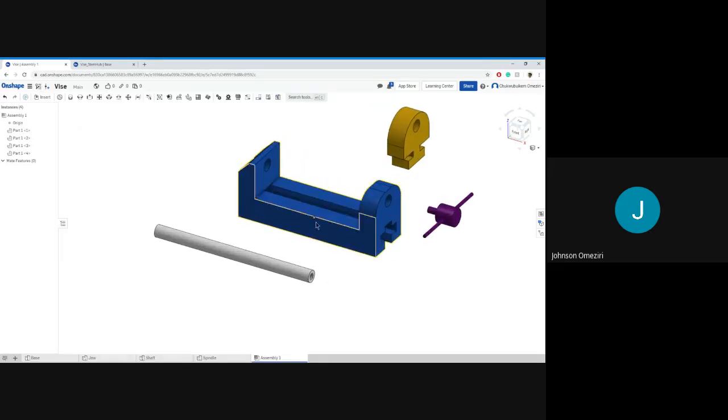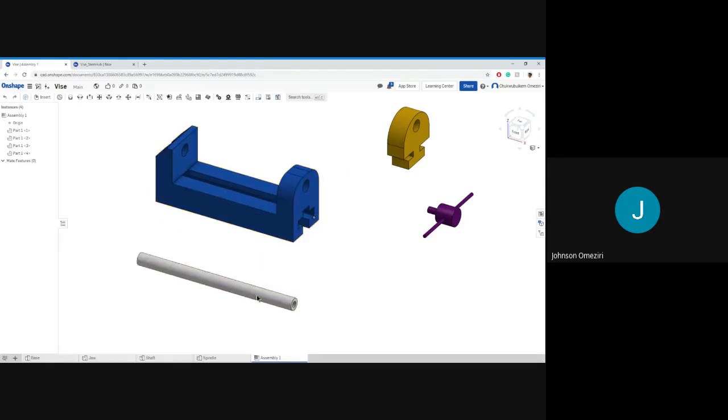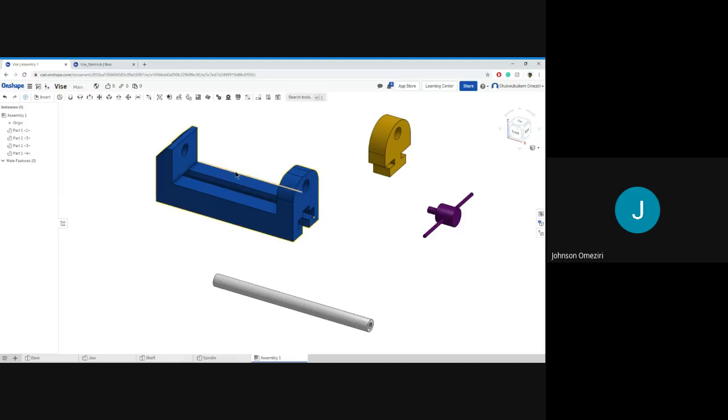In this 3D space now, you see everything here can still move. Everything can just move around. You can move it wherever you want. But if you're doing an assembly, you need to have one part that is fixed, a part that is grounded, so if other parts want to join to it, you need something that can stay in one spot. So right click on this base here, this is the base we're going to be using. Right click on it, and down here you should see the option fix.